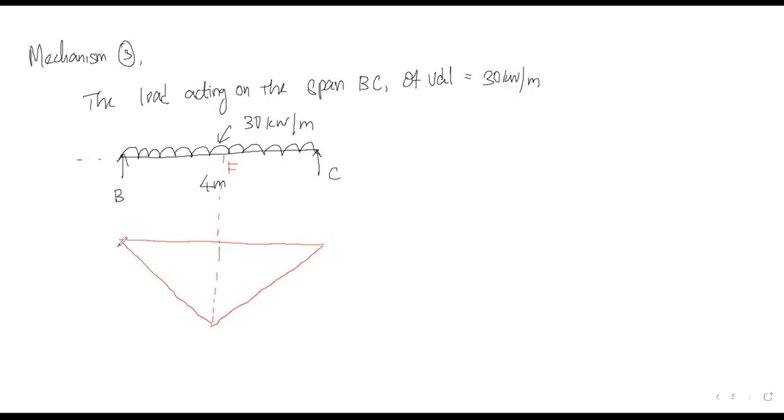So this is continuous support. So we can have plastic moment of MP, and this is end support, that too hinged. So we do not have a plastic hinge, so it will be denoted by an empty circle. And under the load, we can have plastic hinges, so I'm going to have MP here. Now, because of this position, the slope is equal to theta.